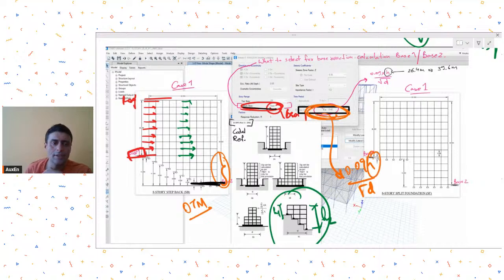In this h height, you take this smaller height, so that you get a more critical time period, and then while defining the bottom story, take this base 2 as your bottom story. Clear? In this manner, it will get applied to different floor levels also. And because you have given your own custom height, you will get the time period that you want, which will be the critical time period. So this is what you can do.